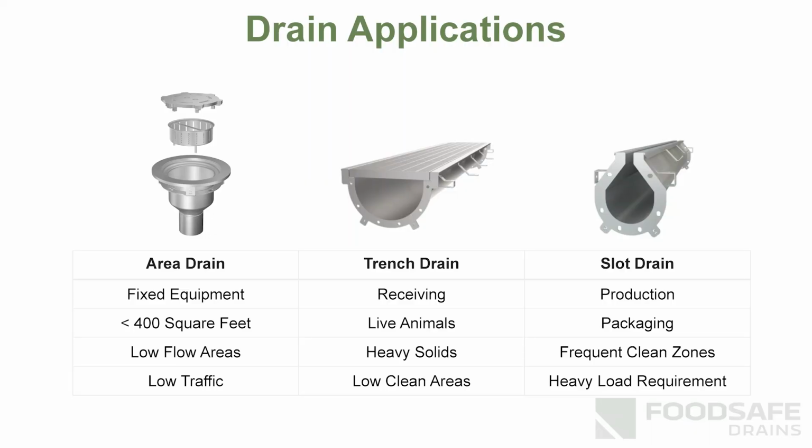But I understand the reasoning behind it. Well, these are easier to clean. They are still unsafe because you've got a lot of lids to remove, a lot of moving parts in them. And then slot drains also have grown hugely in popularity in North America. They are heavy-duty, lasting products that are easy to clean and proven to be easy to clean and able to inspect. So it really just depends what you're using. They're not great for collecting solids.